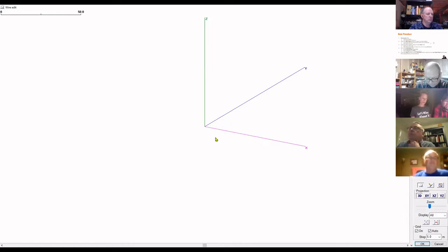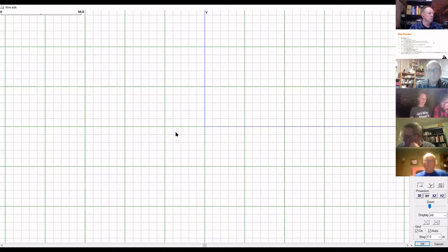So what we want to do is draw our antenna. Because we're drawing a 40-meter half-wave dipole, the best view to do that in is XY. Okay, we just want to look down on the antenna. So imagine you're in a drone looking down on your dipole. Now, one thing that might be tempting to do in this view is to draw it up in the air, because that's where antennas go, up in the air, right? But you need to understand that this is not where you control the height of your antenna. You're just designing the antenna. We'll deal with where it is later.